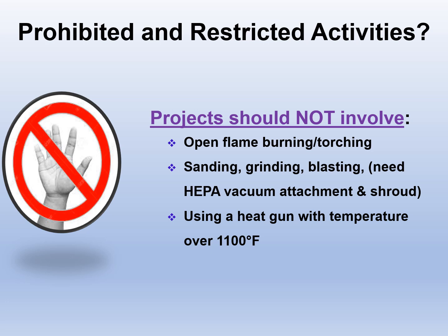In this case, you would need to use a HEPA vacuum attachment with the shroud. In such cases, this will allow good suction of paint chip particles and debris and would lessen the risk of lead-based paint contamination of the surrounding work areas, and it would greatly reduce any potential exposure to the workers performing those activities.